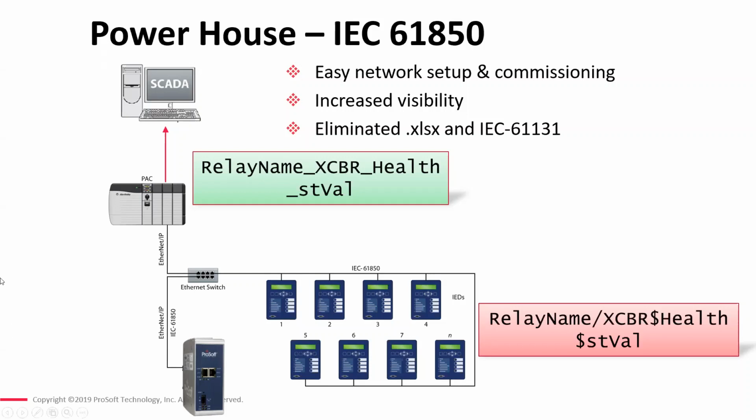There's another question that came through regarding getting sequence of events data from the IED. Sequence of event data is typically brought through as report information, and we can be a subscriber to a report.